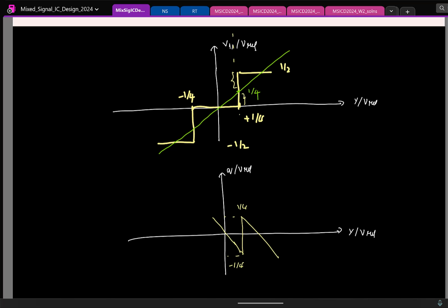Again, the same thing will happen here also. I'm just drawing it roughly. So once again, you can find that even if one of the reference voltages, say this one, goes to the right, you can work out what happens to the quantization noise. It will actually just grow as much as -1. That's all. So in this case also, even if you make an error of plus or minus Vref by 4, gain times the quantization noise will be within the reference voltage.